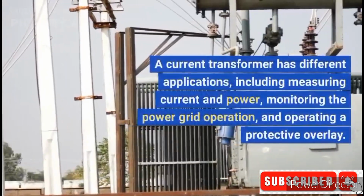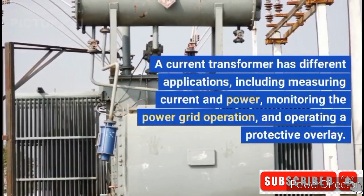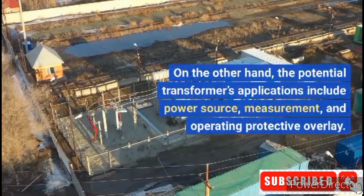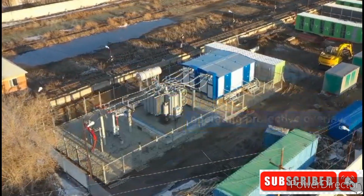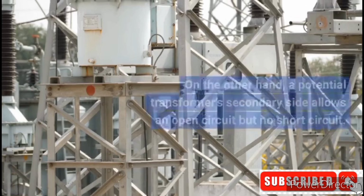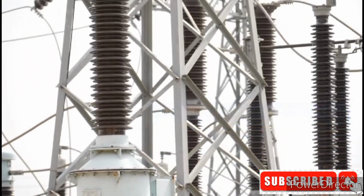Applications. A current transformer has different applications, including measuring current and power, monitoring the power grid operation, and operating a protective relay. On the other hand, the potential transformer's applications include power source, measurement, and operating protective relay. Generally, a current transformer's secondary side allows a short circuit but no open circuit. On the other hand, a potential transformer's secondary side allows an open circuit but no short circuit.